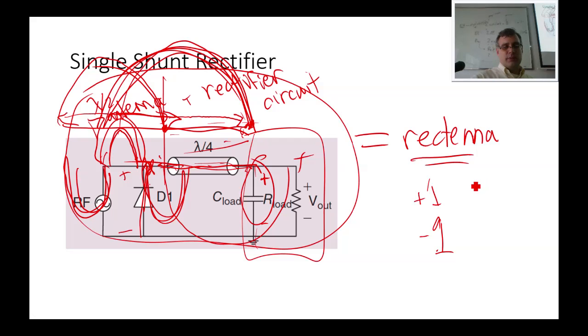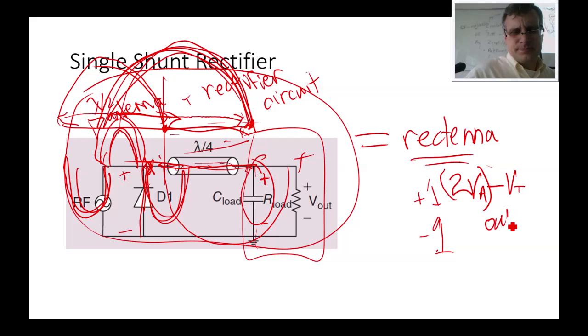So this is going to be very similar. Whatever your antenna amplitude is, minus the turn-on voltage, except you can actually put a 2 in front of here because you're doubling it before you have to turn on the diode voltage. The maximum possible output.